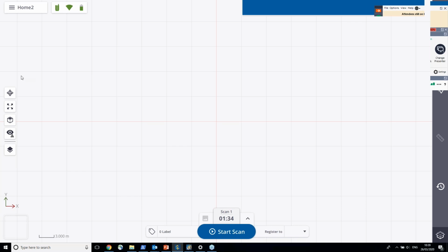On the left side in general is everything that goes on showing and displaying your point cloud as you go along. And then on the right side, we have a little bit more tools. So here you can see whether you have a good or bad registration, the annotation, the measurements, and so on. And basically at the top there, you have a limiter, so you can limit the elevation of the scan if you want to see it from a side view, and so on. This can also be locked. And then at the bottom is really where you control the scan element of what you're doing itself.